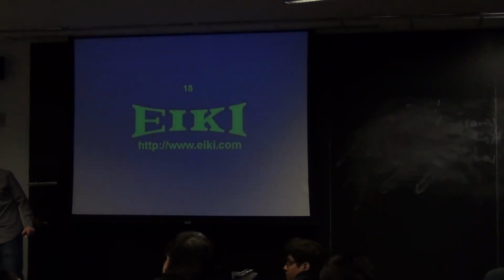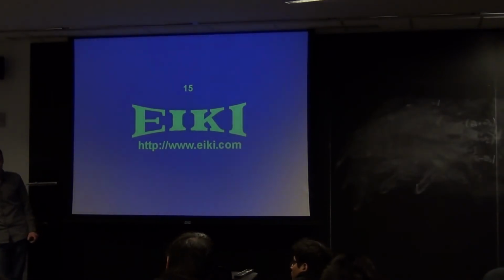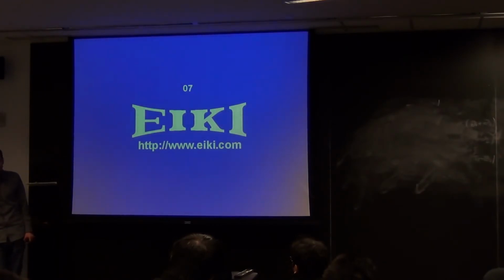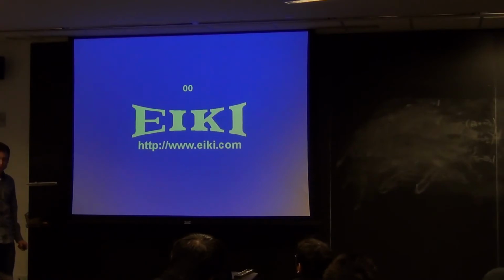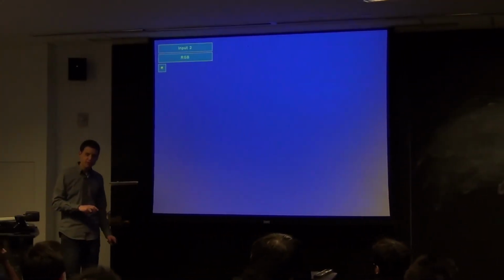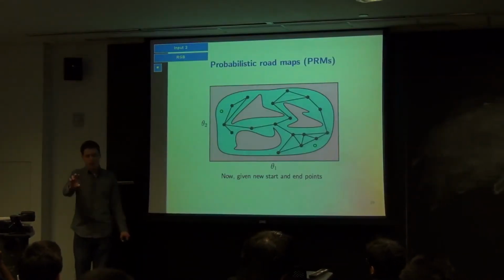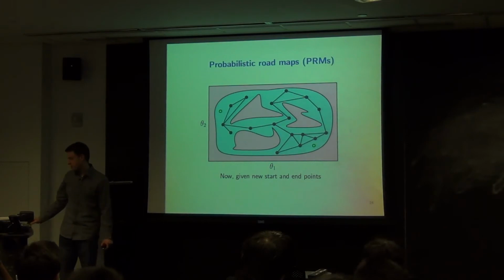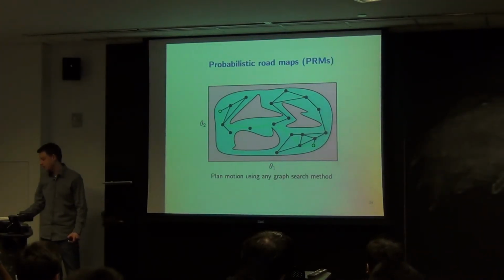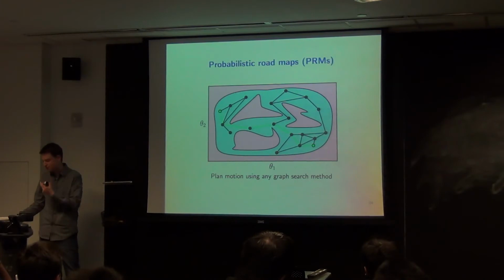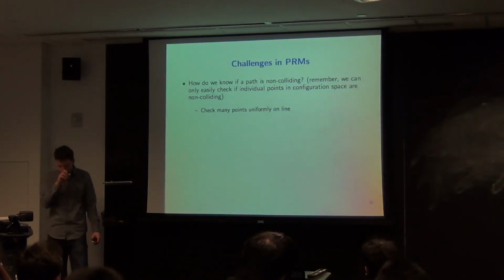Some of the motion in the task space might require large... Oh yeah, actually I'm doing this all in configuration space, right? So the trickiness about going from task space to configuration space is somewhat avoided if you do all your planning in configuration space. Then you have to worry about things like, am I right at the boundary of my reachable set, so that I need a lot of force to maintain the position there. But there are some tricky parts here.